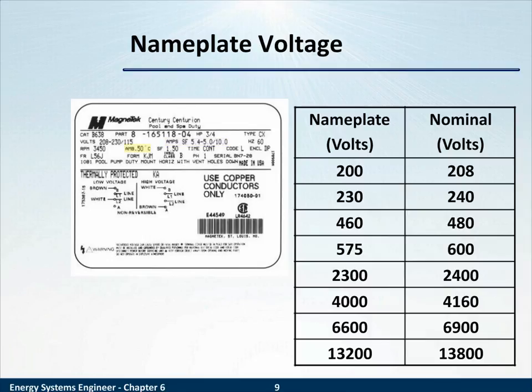the temperature rating or insulation class, ambient temperature 50 degrees C, insulation class. This is called a drip-proof enclosure motor. And then the frame size is L56J and insulation class B. And the last is it is a single-phase motor.